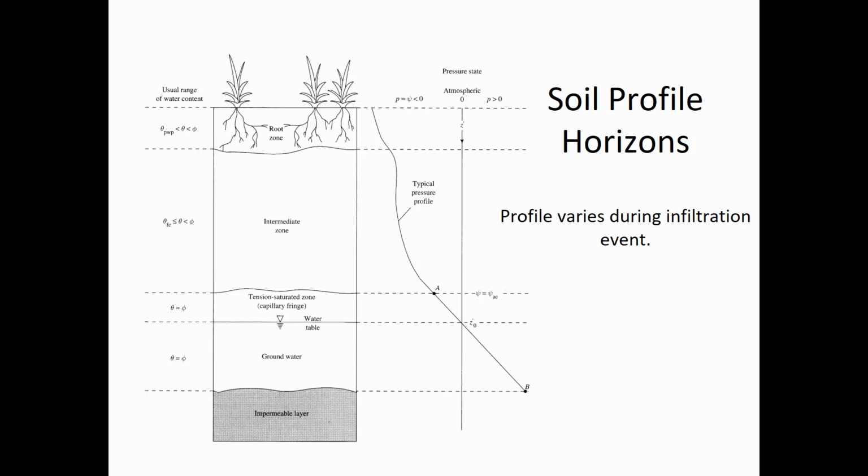But when you're above the water table, in the capillary fringe, there's water that exists under conditions of tension, meaning that the attraction for the soil is sucking the water grains away from one another, and so it's making space between the soil grains for those voids to have air in them in addition to water.